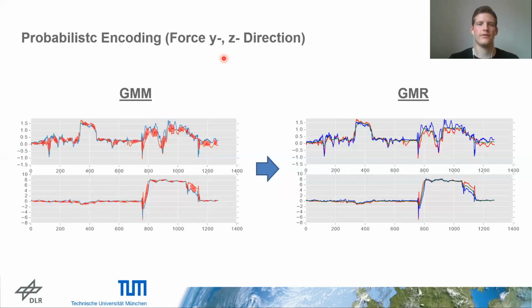We record 15 different sensor values during the demonstration, which include the orientation and the position of the end effector, the forces and torques acting on that end effector, the gripper finger distance, and the grasp status, which indicates if an object is grasped at the moment or not.